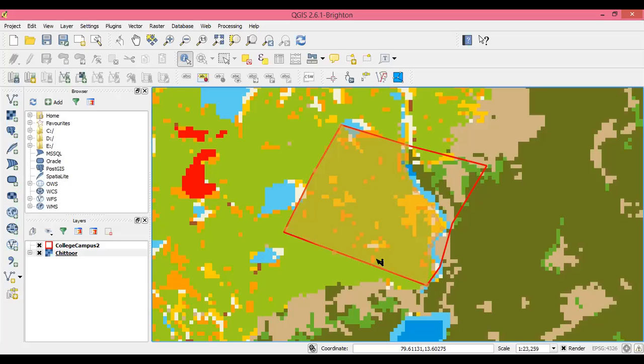That gives you the size of the drain required, right? So if your drain is able to handle the peak runoff rate, then it will definitely be able to handle whatever other runoff is generated, right? So your objective is to find out the peak runoff rate, for which you need the peak rainfall intensity.